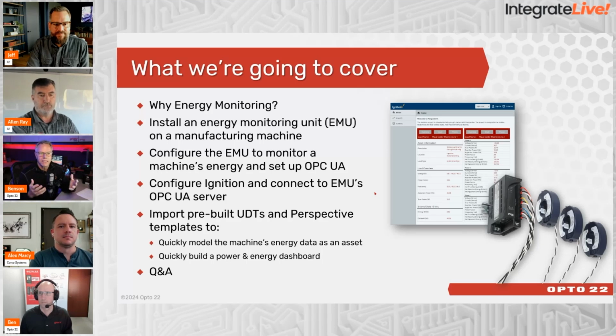Then we're going to take what's called a groov RIO EMU. It's a little product that Opto 22 provides, and it's an energy monitoring unit. We'll talk a little bit about what an EMU is, and then we're going to configure that EMU, again out of the box, literally commissioning it, getting it set up on the network, getting an account in there, and configuring the parameters of the load.